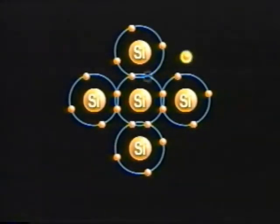Once dislodged, the electron no longer belongs to its original silicon atom and is virtually free to move from one atom to another. For this reason, these dislodged electrons are more commonly known as free electrons. After the electron leaves, a space is left behind in the valence shell. This space is called a hole, and it serves an important role in semiconductor devices.